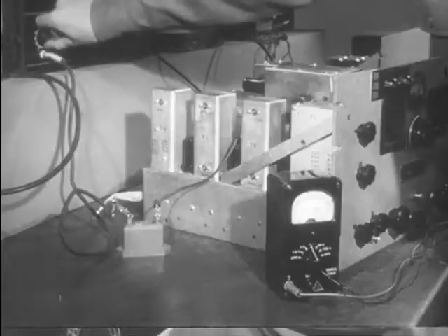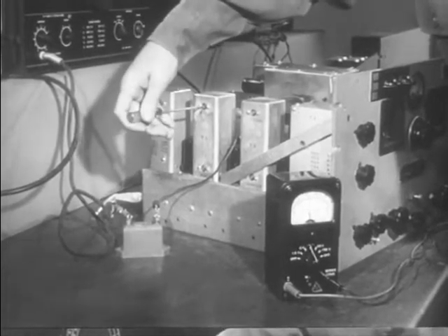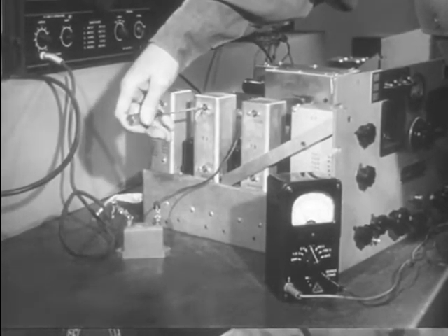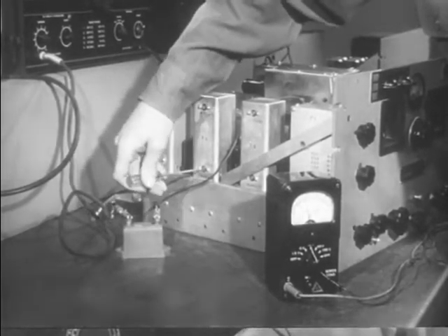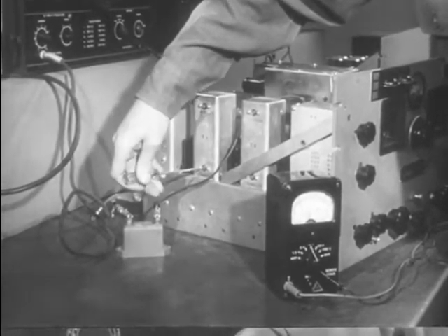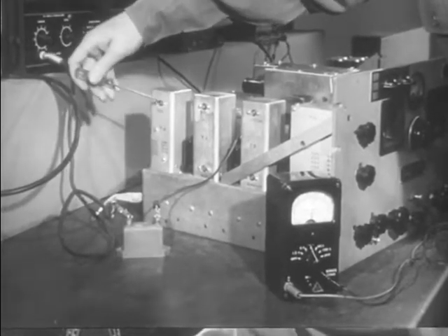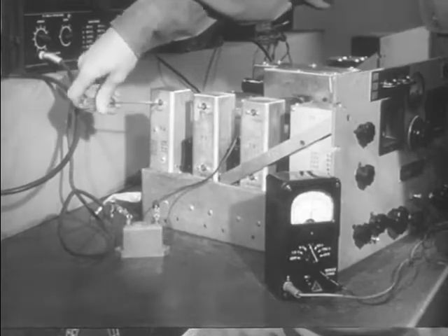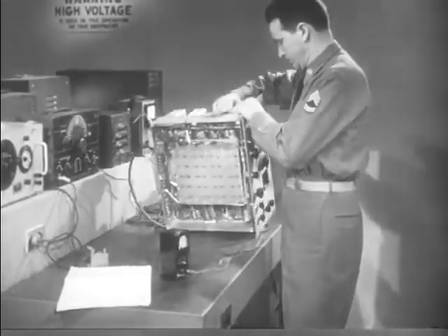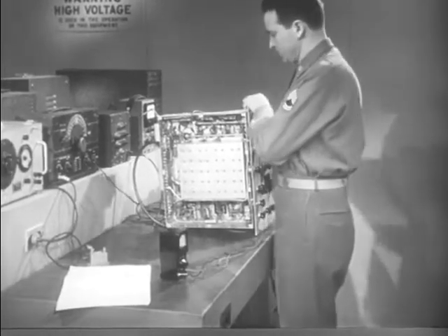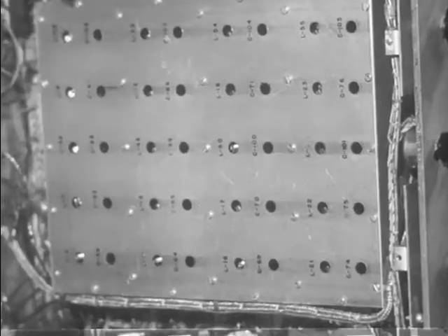The goal here is not an exact meter reading, but the point of maximum deflection. The adjustment screw is always turned past the point of maximum deflection, then back and forth 2 or 3 times. The oscillator and RF circuits are aligned in a similar manner, but on different frequencies.